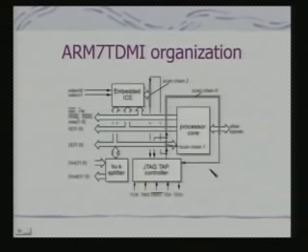From that PC, I have generated the code and I would like to run it on your ARM. So, one option is you load it onto a memory and connect that memory area to the processor core. When it boots up, the initial memory area will contain the instructions and it will start execution from that. The other option is using this JTAG port, using a JTAG connector.